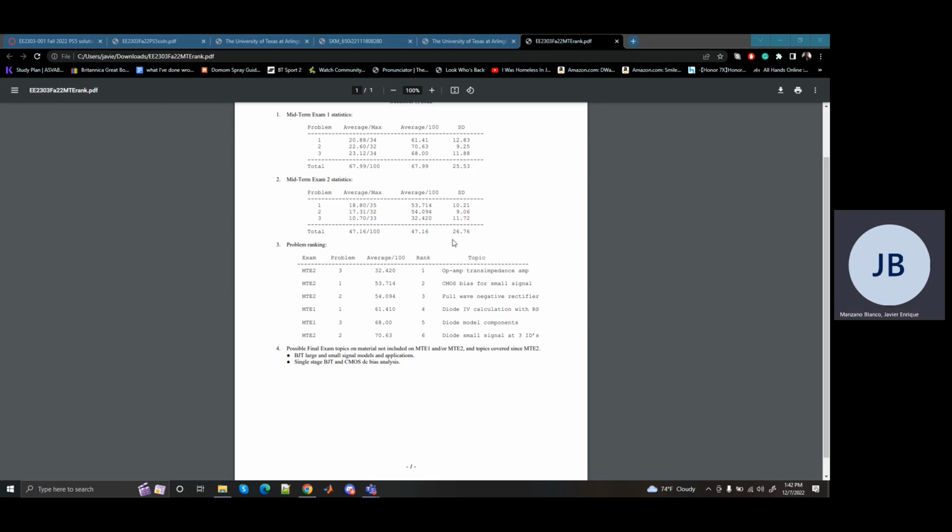You can put a capacitor here because in the DC case, these two are just in series, right? So this RE can be different than the RE in the AC case. Because if I have this capacitor here, in the AC case, this shorts out. So now RE is just this. It changes it and it helps us adjust the gain in the AC.